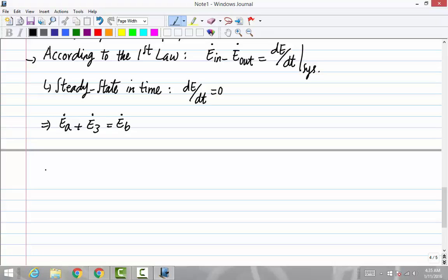And according to the equations that I gave you before on the notes, I can substitute the overall mechanical energy of this E dot sub A and E dot sub B here. So I would have, this is the famous equation, velocity square over 2 plus g za plus, likewise here at point B, outlet.